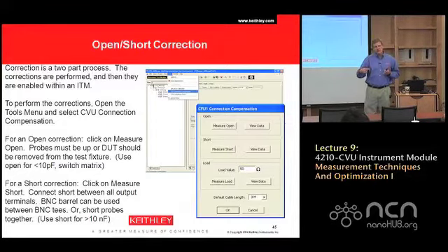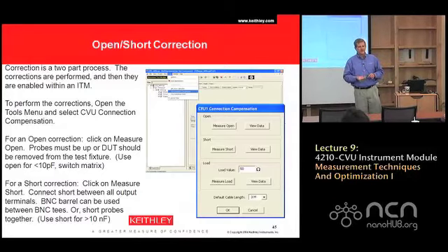We chose not to. We chose, in our range of 1 kilohertz to 10 megahertz, to do 10 points per decade. In other words, we've got 1, 2, 3, 4, 5, 6, 7, 8, 9, 10 kilohertz, 20, 30, 40, 50 kilohertz, etc. We chose 10 points per decade. We chose that for a reason. That allows us to do 100% frequency calibration at the factory.